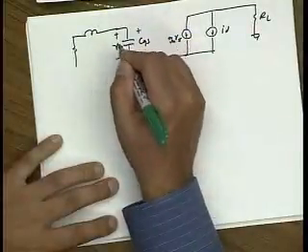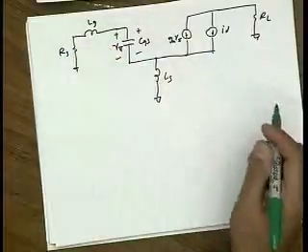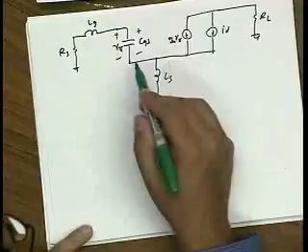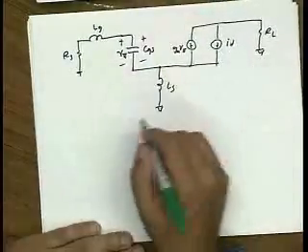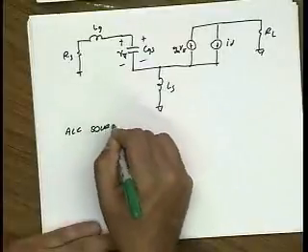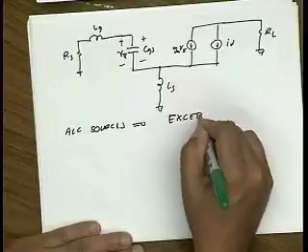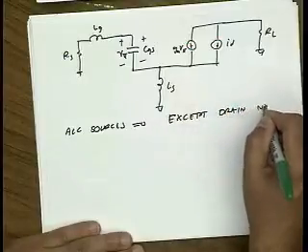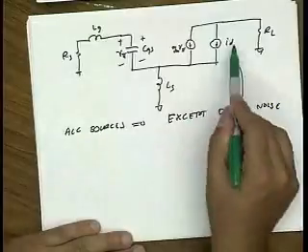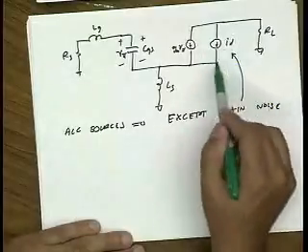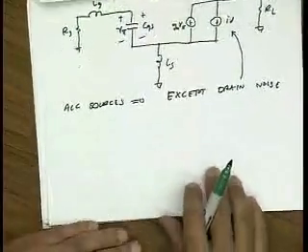So pay attention. This will also help you on your homework, because you're going to do a similar analysis in your homework. All right. So what I'd like to do is calculate V pi for this circuit. And I've set all sources to 0 except the drain noise. Okay? And for this analysis, instead of assuming this is a noise power, we actually assume it's a real signal and keep track of its phase, because phase is important here.